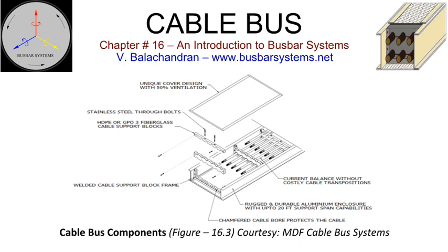For indoor installation, the top and bottom sheets are punched to facilitate the cooling of conductors, cables, by natural convection. The preferred width of the punch slot is 6 mm, 1/4 inch. In the case of outdoor installation, the top sheet is plain or louvered to prevent direct sunlight, rain, and snow from falling on the cables. The top sheet can also be sloped to prevent the accumulation of snow and wash off the accumulated dust.